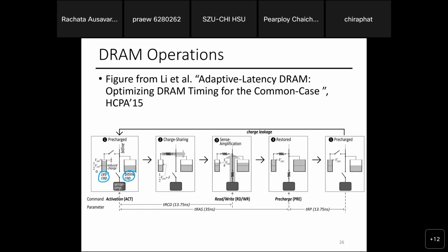Second thing, every row shares this bit line. The bit line, imagine the wiring that goes through all the rows. And you have one much bigger capacitor, which we call the bit line capacitor. Think of it as a pool, a much bigger capacitor that I can measure and put electrons in. Okay? With me so far? No. All right, when you store a bit in your DRAM, you need the cell capacitor that stores your bit.